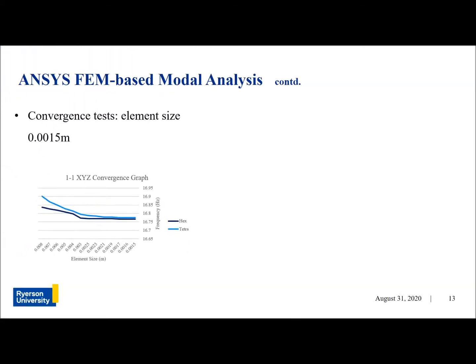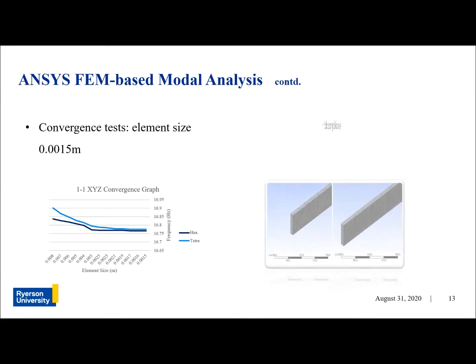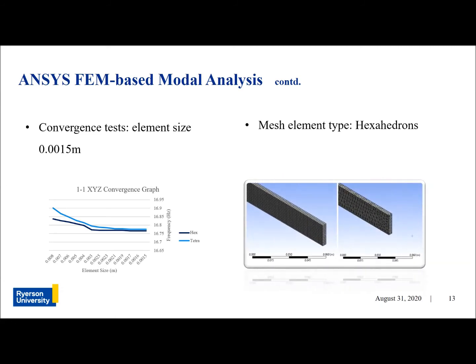Because mesh design is an important feature in simulation, the mesh type and size were studied in this research. Tetrahedral, hexahedral, polyhedral, and pyramid are four major types of 3D elements commonly used to discretize the domain in FEM simulations. However, using ANSYS Academic, my access was limited to only tetrahedron and hexahedral elements.